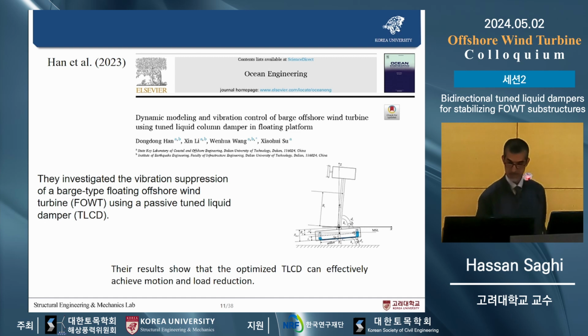And finally, in this paper from Han et al., they investigated the vibration suppression of a barge-type floating offshore wind turbine using a TLCD.